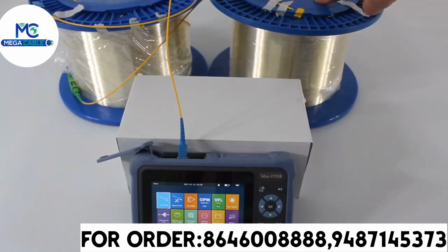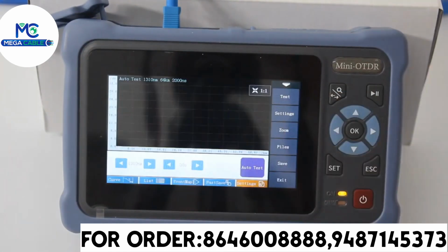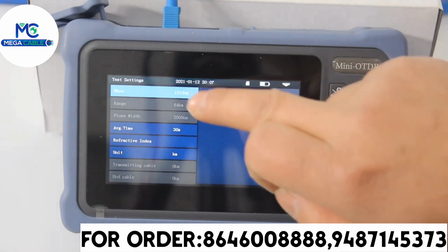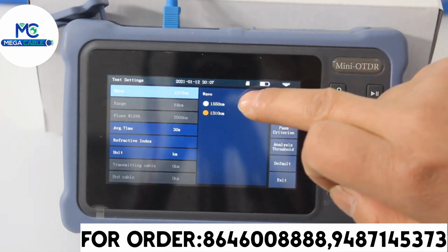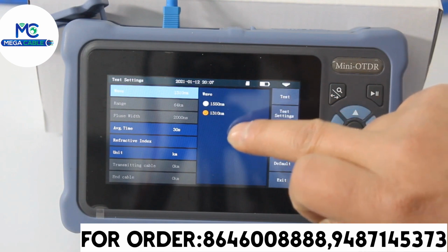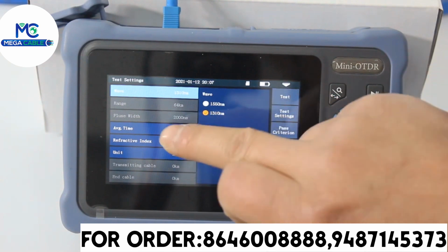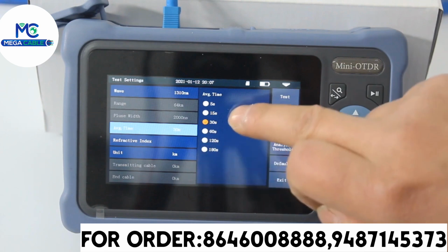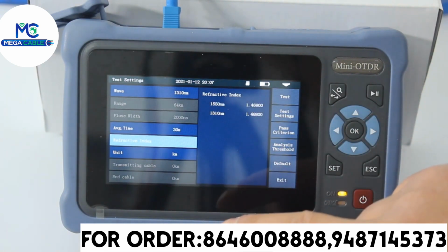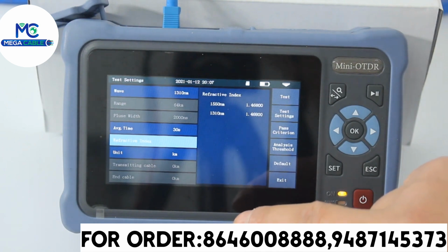This is a 10 km fiber spool and a 20 km fiber spool. Click Auto OTDR. Click Settings. For this OTDR, there are two wavelengths, 1310 and 1550. We select 1310. For average time, select 30 seconds. For refractive index, please ask your own cable manufacturer.